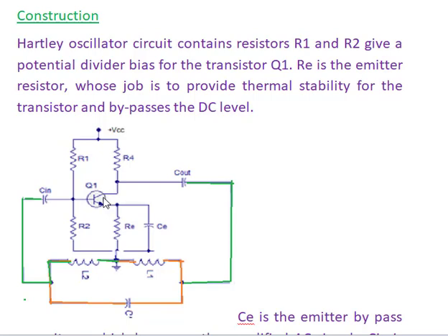And the collector of the transistor Q1 is biased using the resistor R4. The collector is always given a reverse bias. So, it is NPN, so the n-type material. So, the positive voltage is given to the collector of the transistor through the resistor R4. We already know that Cin is the blocking capacitor which blocks the DC voltage from the biasing voltage source from passing through this capacitor. Actually, it blocks the DC voltage.